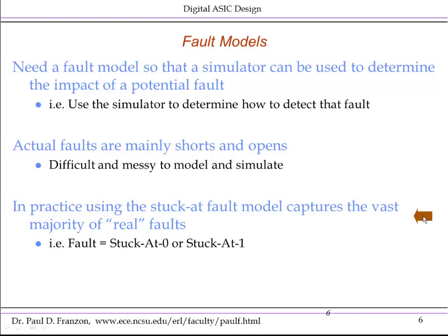So this kind of approximates how the real faults manifest themselves on the chip, and in fact works out very well. I'm not going to show this to you, but you can show that using a stuck-at fault model allows you to actually evaluate most shorts and opens, but the vast majority of shorts and opens. So this is a very useful fault model, and the one that's ubiquitous throughout design DFT.